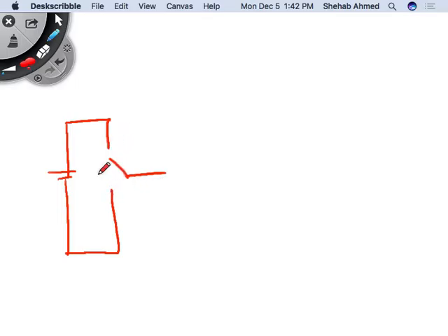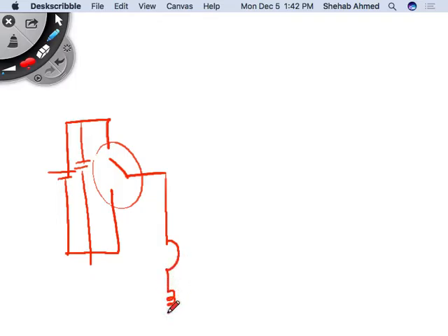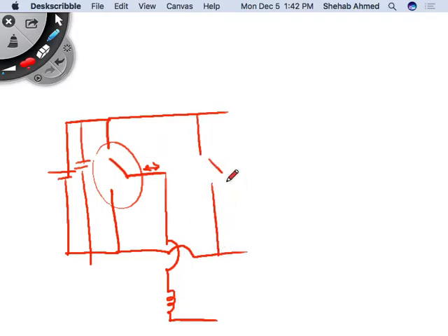Remember, we always said that these two switches will have a stiff voltage across them and a stiff current at the output. The three-phase inverter doesn't differ at all. Here there's stiff voltage across the two devices, and a stiff current at the output. This is for one phase, another phase, and the third phase.